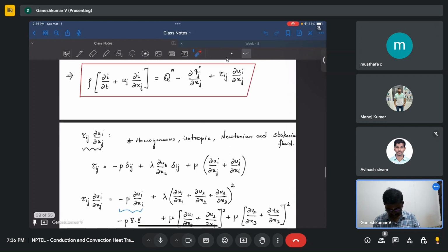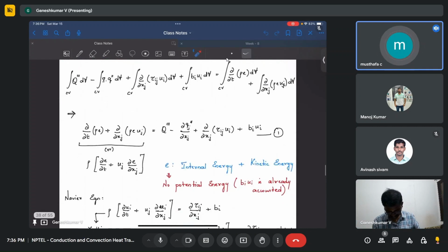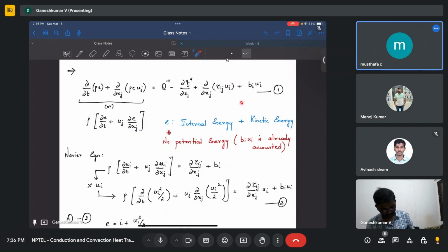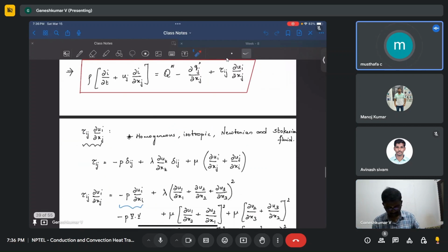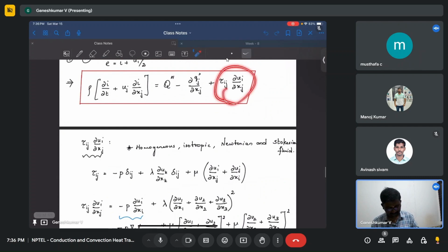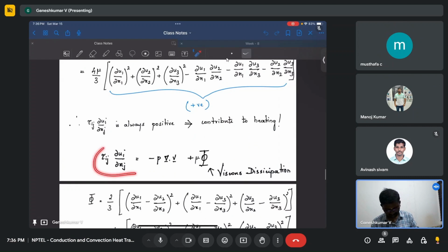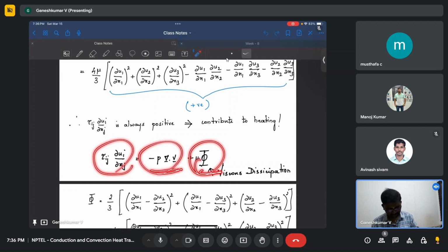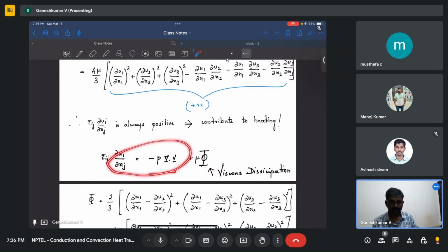So this is the total energy equation, right? In the derivation, the last time I'm asking about. You have this stress term. This stress term will give rise to, for example, in the internal energy equation, this viscous dissipation. I mean, this stress term will lead to 2 things. One is viscous dissipation. The other is pressure work. So these are coming from the stress tensor. So this is what the flow work is.